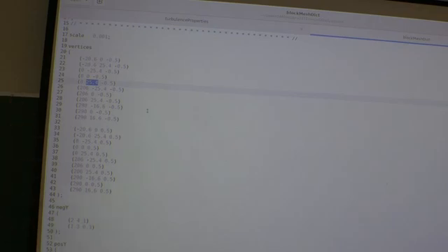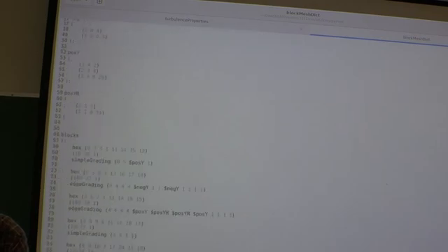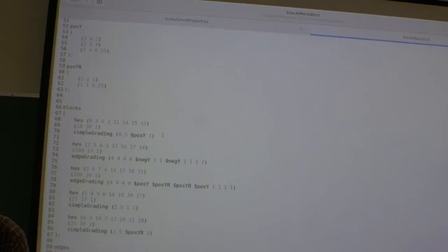So yes, you have a whole bunch of corners, define some values here, and then you have several blocks. And how these are organized, that's my point, where you could have help from this paraFoam -block. Then you could see the different blocks, how they are organized. They have some simple grading and some edge grading. So the meshes are not uniform, they are stretched a little bit in the different directions here. Coming back to that one later.